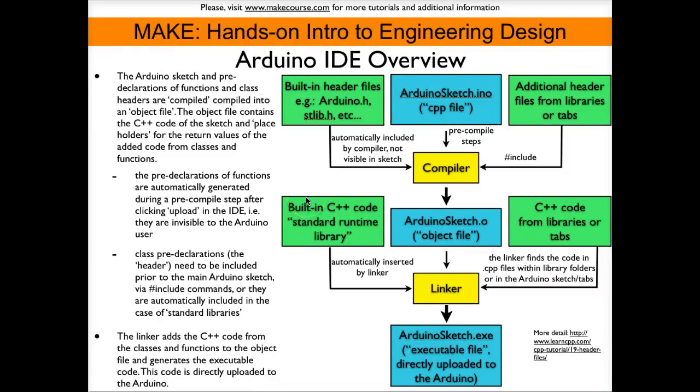Let's summarize what we did in this tutorial about libraries. First, we started out with an Arduino sketch that had the class definition in the main sketch file, and then we put it into a separate tab, and we used the include statement to make the compiler aware that the class is now defined in a tab.